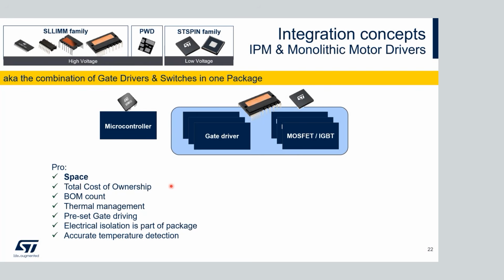two screws, right? Or with the monolithic motor drivers, you cool through the PCB. The thermal management is easier because you already have electrical insulation through the package. And you have an accurate temperature detection, for instance, by an NTC, if we think about the intelligent power module. The monolithic motor drivers have an over temperature protection embedded by default, so they will also disable if they become too hot. But there's always a but.